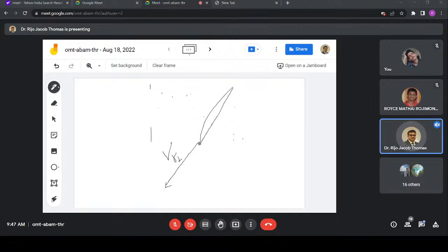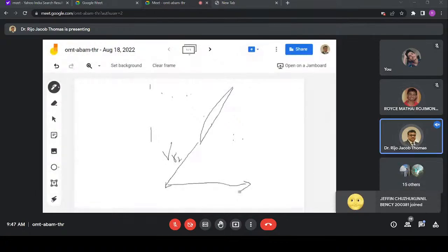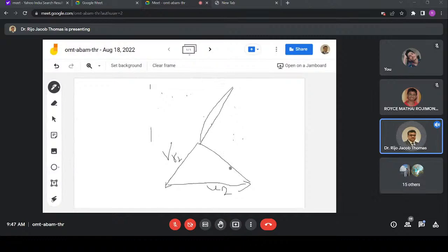but the blade is moving with some velocity at this end, u2. So I have just drawn that u2 here. That is u2. Then combine this. That would be my absolute velocity, actual velocity of the air. So that is v2. So if I resolve this v2 into the flow component, this would be my vf2, and this part would be my VW2.